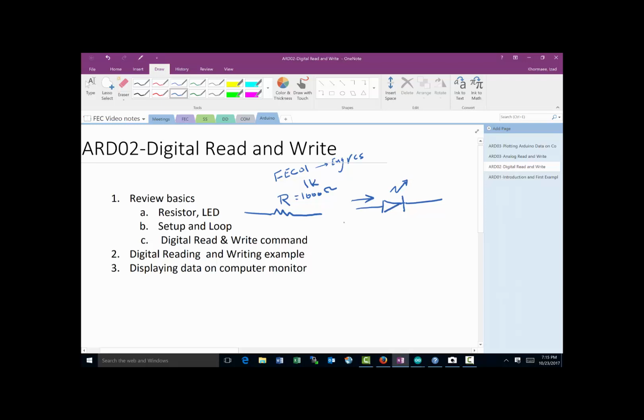All of these we're going to use are what we call through-hole type, bigger devices, so I can handle them with my hand. All of these devices also come in surface mount, much smaller, if you're trying to go to production. But for now, it's much easier to get the through-hole version, because then you can play with them. Okay. Now that we've talked about these two, let's go take a look at them.